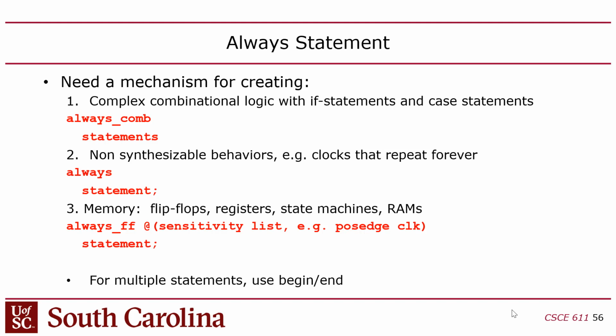If you have code like this, it's valid code. Well, actually, it's not valid. You'll get an error because you explicitly said always_comb. The compiler would say, hey, I think you screwed up because you said always_comb, but you got a latch in there. However, if you said always @(*), then it won't generate an error message, but it'll still create a latch. And this is essentially an unwanted behavior. This is a bug.